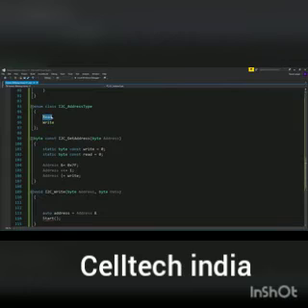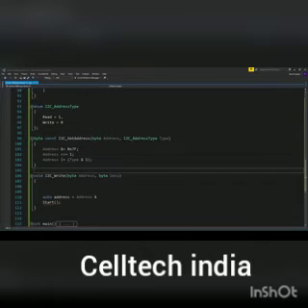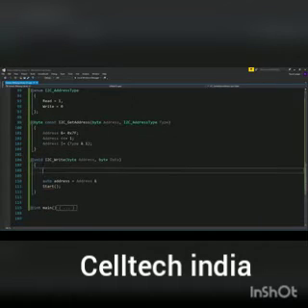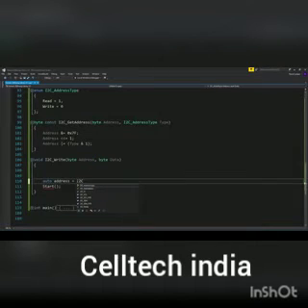So we need a function that converts a 7-bit address to the 8-bit data address, and that function is going to take whether it's a read or a write address, and that read or write is the lowest bit of a byte. So all we're going to do is mask the address to make sure it really is 7 bits, then we're going to shift it across so we have room for that read or write bit, and then we're going to OR in that bit.